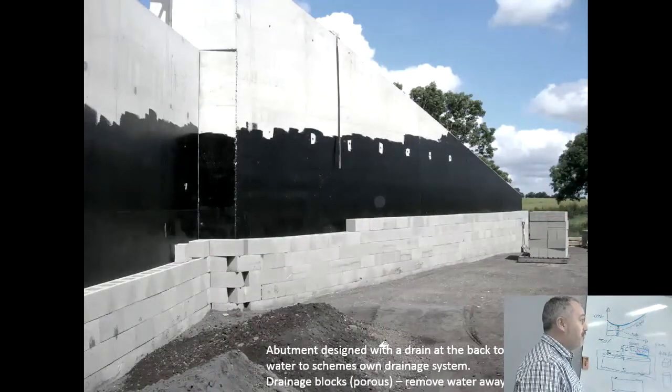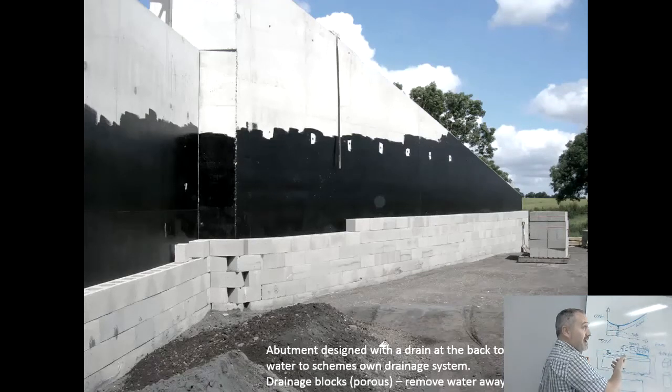Whenever I've done concrete repair, I've always worked with a company called Sika, where you get their grouts that can adhere to the concrete and make sure it's not going to pop off. Because sometimes if you just put concrete in a hole, as soon as you get a bit of rain and then the frost, it'll just pop it off.